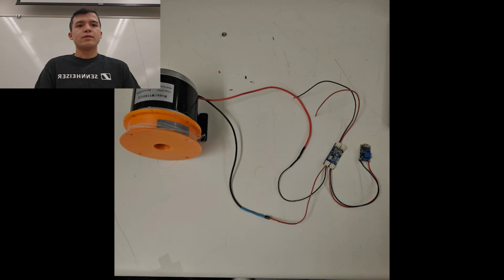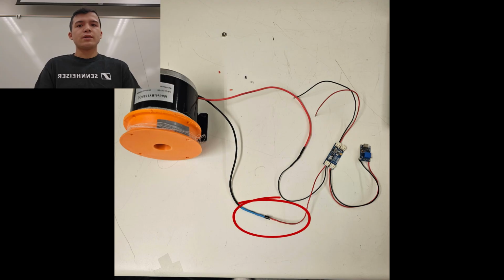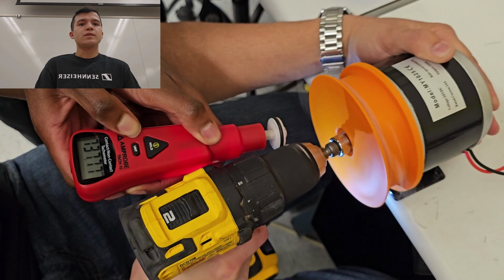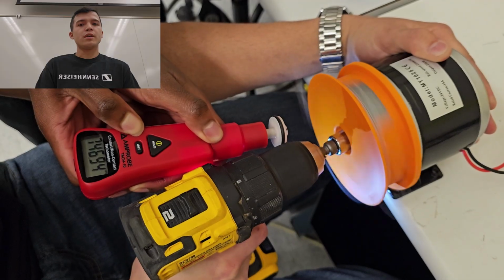Before proceeding with charging the battery with the generator, I initially connected the generator and battery to the charge/load controller. Unexpectedly, the generator started spinning like a motor due to the back current caused by the battery. To solve this issue, I installed a diode in series with the positive line from the generator to the charge/load controller. To charge the battery with the generator, I used a drill to spin the generator as close as I could to a constant 800 RPM to simulate the RPM input we are seeking from the gearbox.